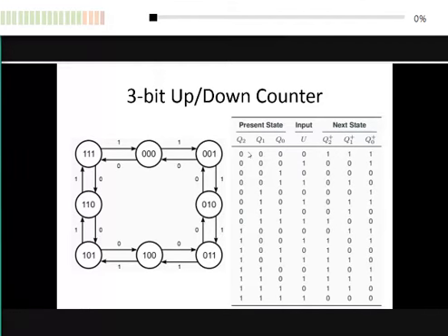Okay, you should have one group of Q0, Q1, Q2 as J, and then you have one group of Q0, Q1, Q2 as K. Two groups. For T flip-flop, this remains the same as this, but the sequence of the next state is not the same as in the D flip-flop. It's different. Okay, you can see on your own. That's one way to reduce the complexity of the next state equation.